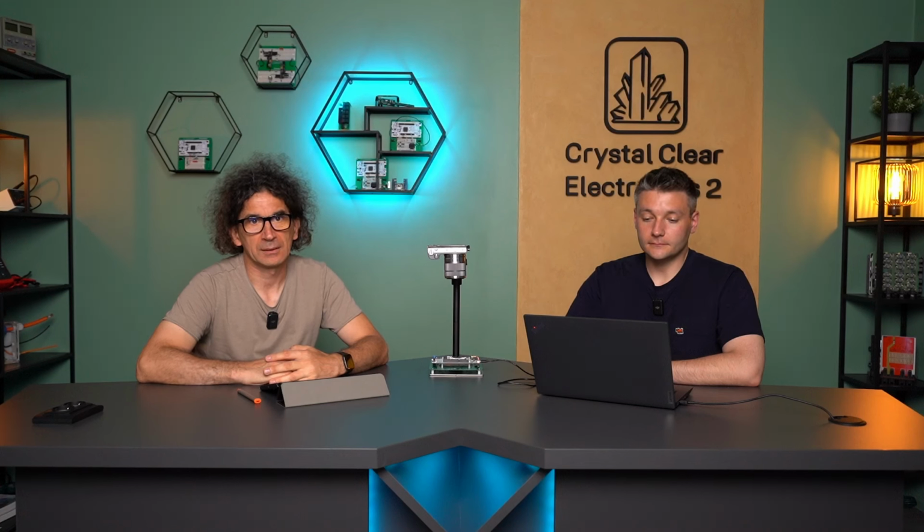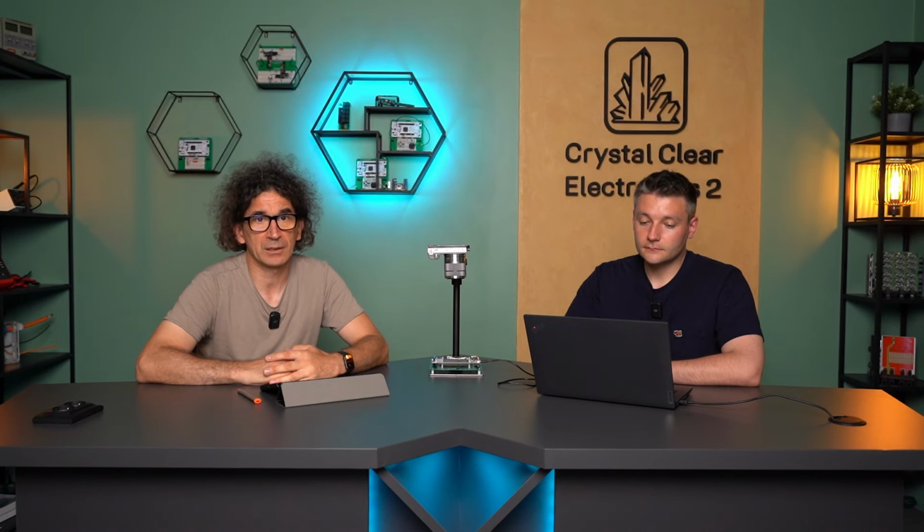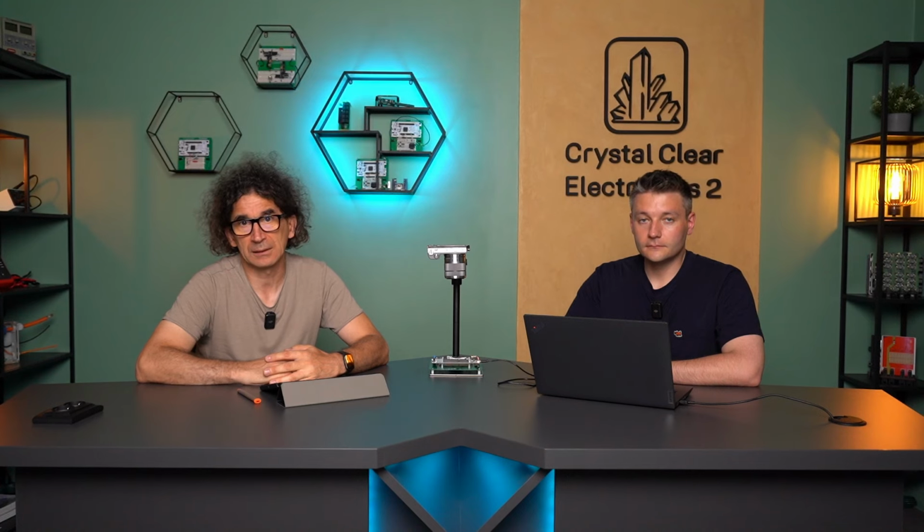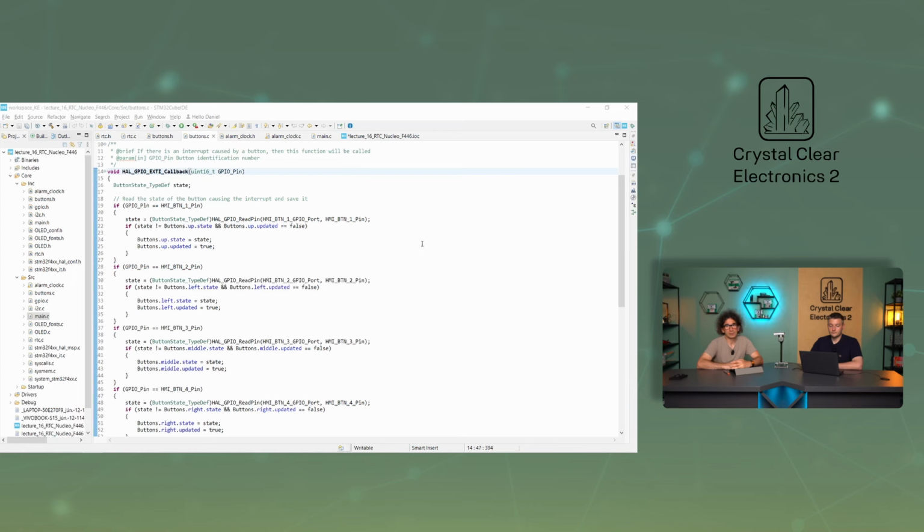We've already been introduced to the concept of bouncing in Chapter 7. To repeat, it's the fact that one button press is perceived by the controller as more than one, because the metal contacts inside the button do not make contact once at the moment of pressing or releasing. The code also includes a kind of debouncing by having all edges generate an interrupt, and the HAL_GPIO_EXTI callback that runs at the very end will always record the correct state.